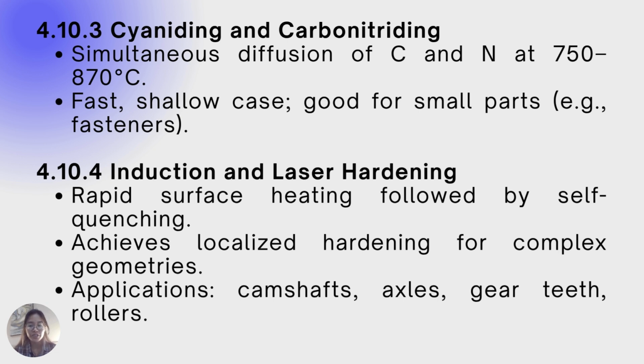Now, carbonitriding and cyaniding. The purpose is to add both carbon and nitrogen for enhanced surface hardness and wear resistance at a lower temperature than carburizing.